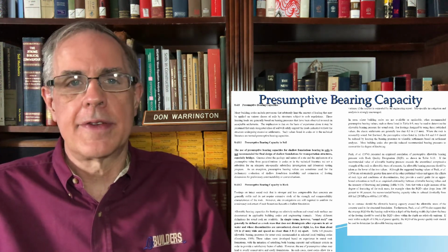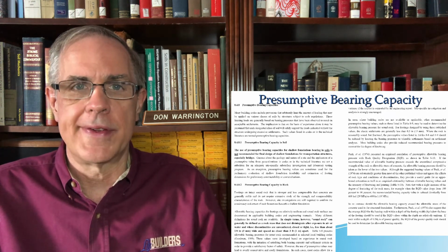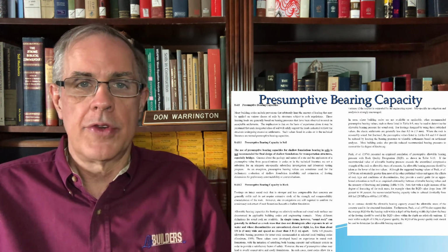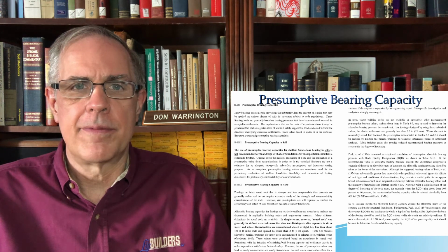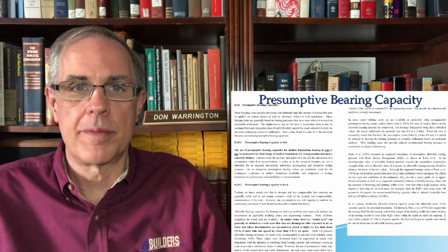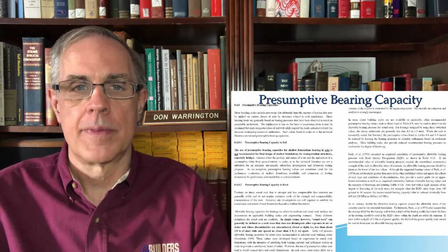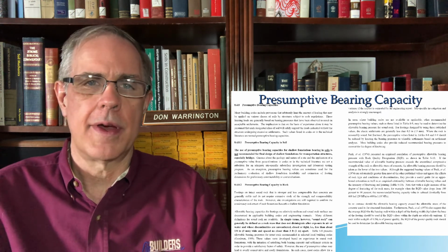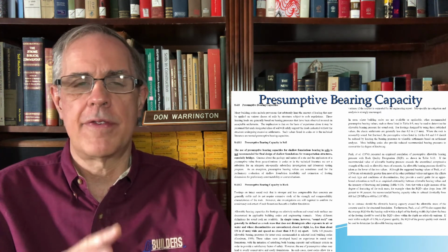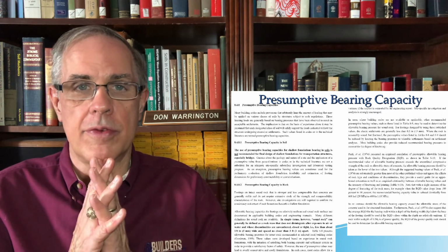Now it comes to the very last topic, which is presumptive bearing capacity. I said I thought the last one was the last one, but this is really the final. Traditionally, shallow foundations were designed using a presumptive bearing capacity, or at least the codes were set up that way. Basically, they would say, for this soil, don't go beyond 500 psf or 1,000 psf or whatever, and this is the way you should design your foundation.